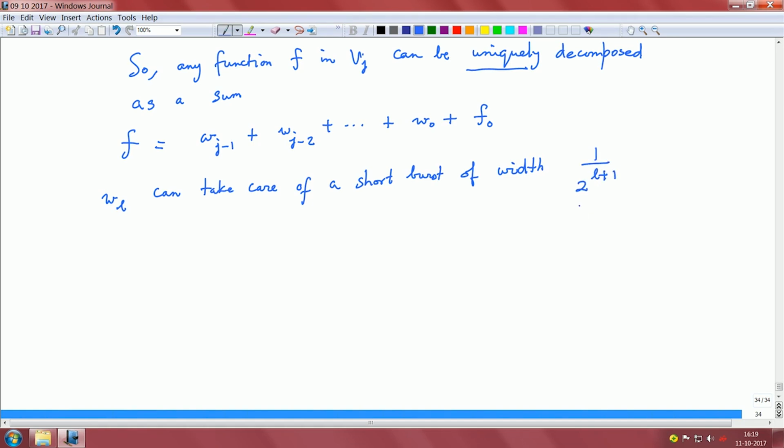So, I initially mentioned if you were to do denoising or remove these spikes or clean up the signal, then you have to identify to which scale you would want to do the wavelet decomposition, then I would figure out those spurious spikes and then just null them off, right.